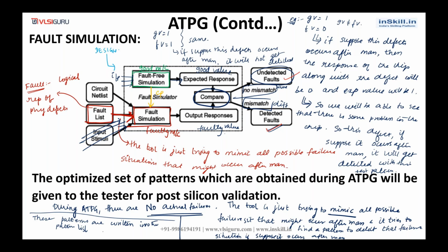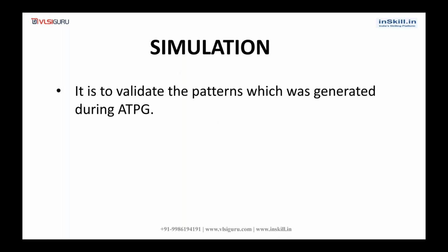And next one is the simulation. So simulation is actually to validate the patterns that are generated during ATPG time. We have seen that at the time of ATPG, the tool was generating test patterns. In order to check whether proper patterns are generated or not, the patterns which are generated during ATPG will be used to test the chip